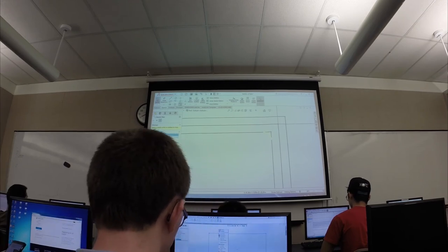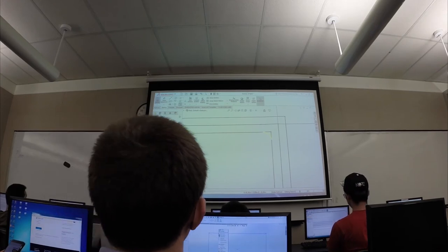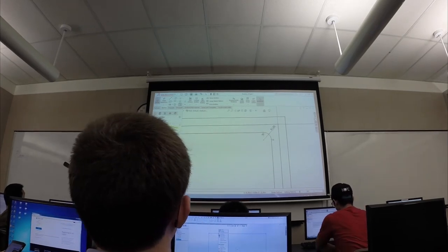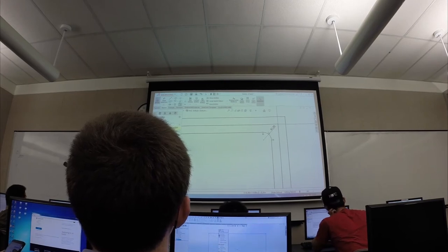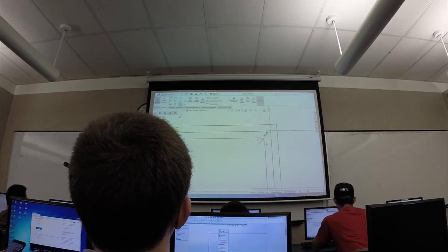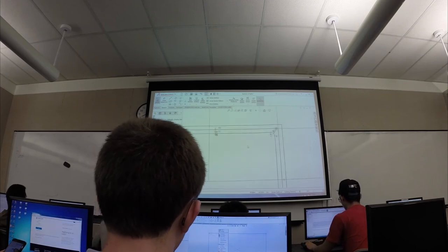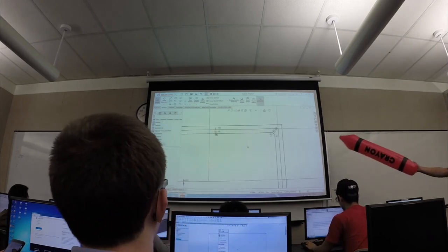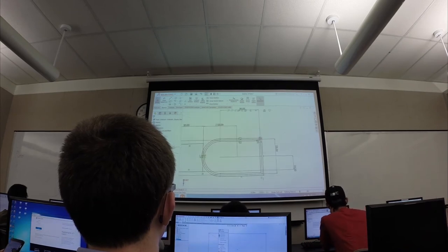You see this yellow line is a preview of what it's going to look like, right? As soon as you click OK, that sharp corner's gone, and a little corner radius replaces it. Just like any dimensioning, as soon as this comes up, we're able to mess around with it and change it, but we're going to keep it for now. Cool. So now we have a little radius in that top corner, and we're going to do a little chamfer on this bottom corner.